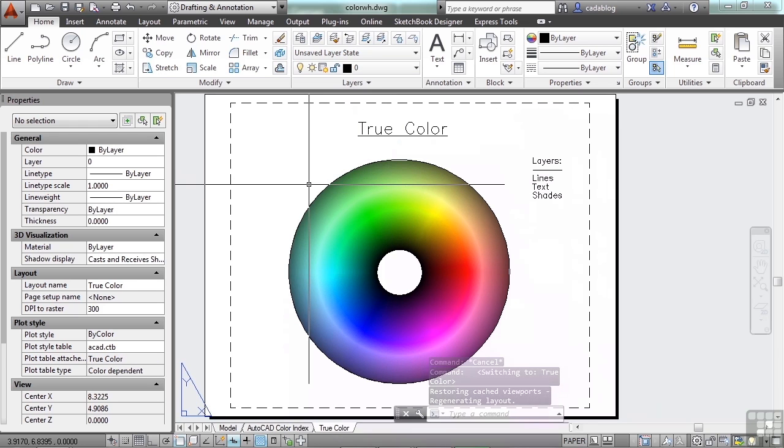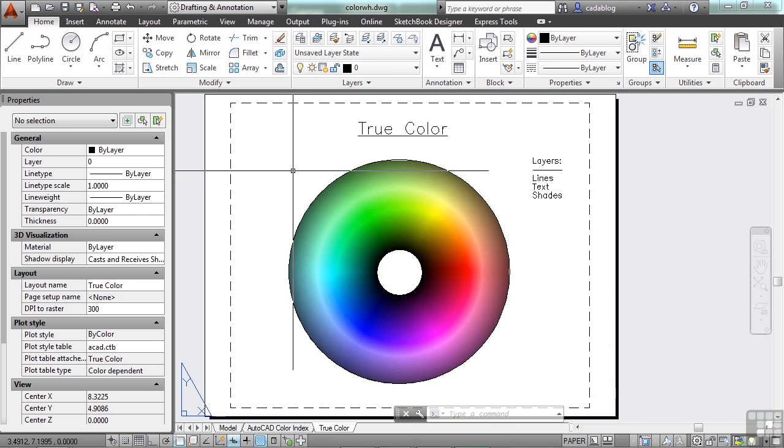Now, you can print from anywhere in AutoCAD and at any size, meaning that either model space or paper space can be printed from. That's fine. It's suggested that you set up your drawing to be printed from paper space though, and I suggest that too. There are several ways to start the printing process, just like with everything else in AutoCAD.